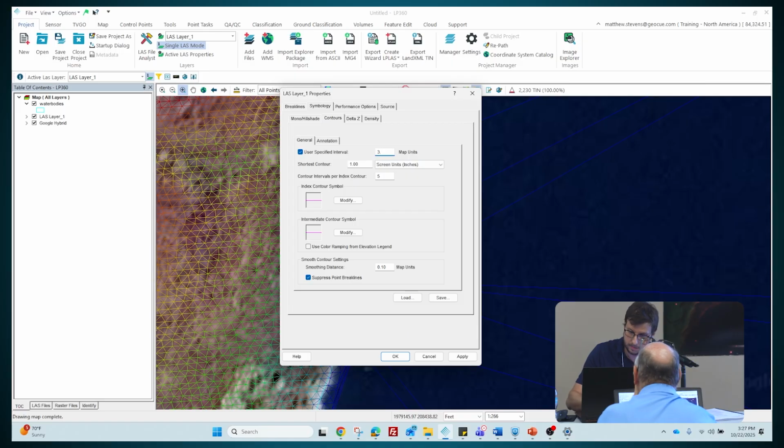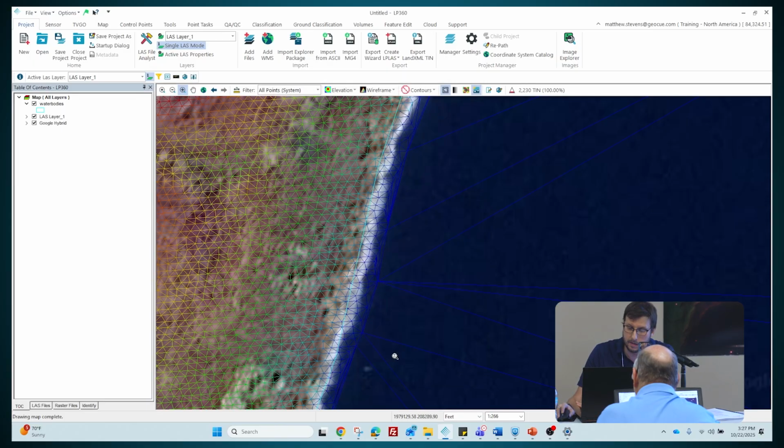That's right here in the middle of the dialog. All the other settings you can leave by default; it should be set like this. Just let me know if you're having issues with that. Click OK. And then you can click on the contours button again at the top, the drop down, and click smooth contours, and it'll start displaying them.